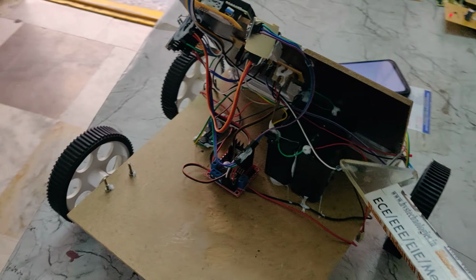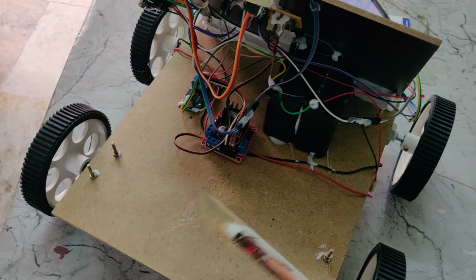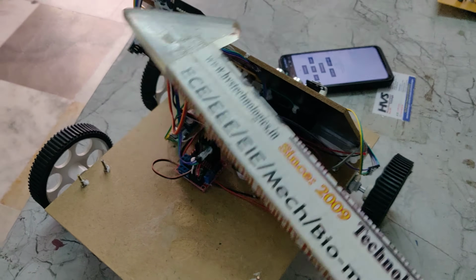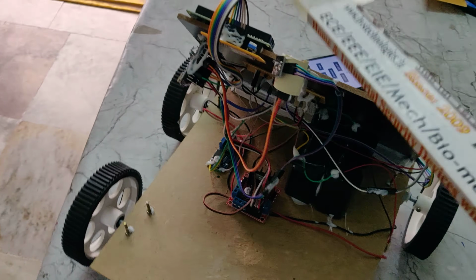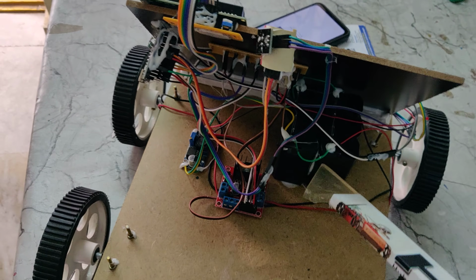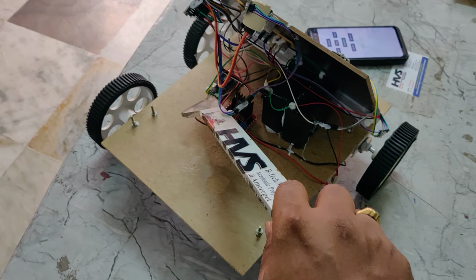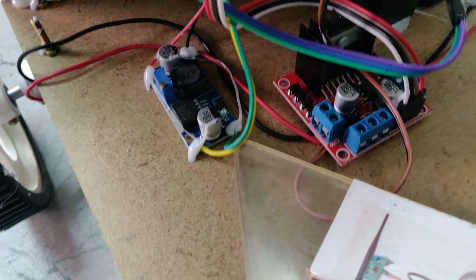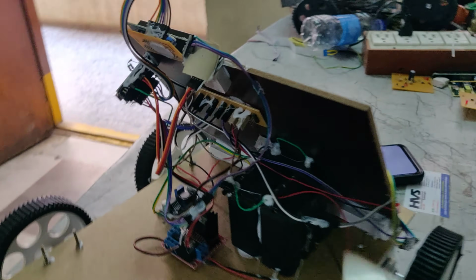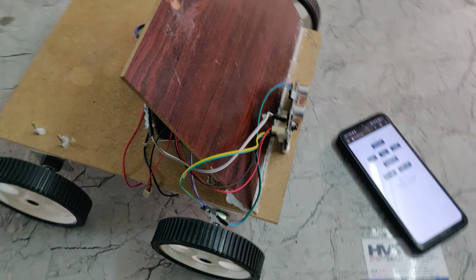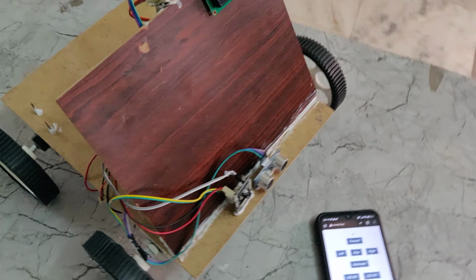Next, the output of this 12 volts DC is input to the motors through the L298 motor driver. The operating voltage of the microcontrollers, the Nano board along with the camera, sensor modules and display, is 5 volts. To convert the 12 volts DC to 5 volts DC, we are making use of this LM2596 voltage regulator. This one is the LM2596 voltage regulator, and this is the L298 motor driver. This one is the breadboard to distribute the 5 volts power supply throughout the modules. Once the LM2596 provides the 5 volts, it is distributed throughout the input and output modules.